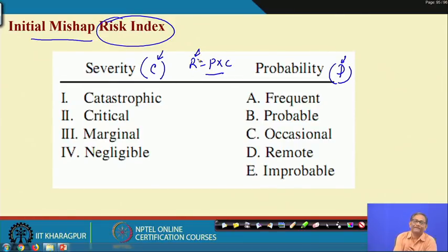That is quantified risk, which is basically objective in nature, then it is quantitative risk assessment. The scheme adopted in PHA is usually qualitative risk assessment, not quantitative risk assessment, because quantitative risk assessment requires data of probability and consequence values, and that too for every top level accident or every hazard you have to find out, then it will be a huge task.